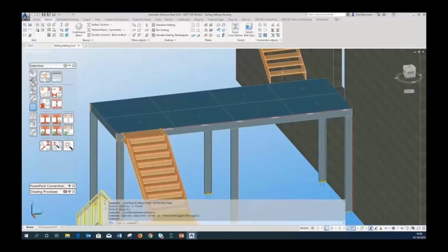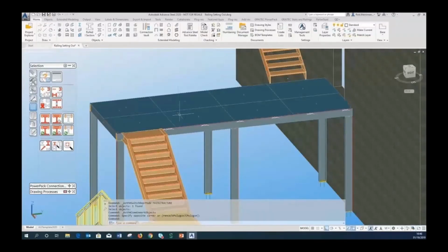And another way you can do separate lengths of railing to manage the panels is to actually use the macro on separate occasions. So on this platform here, I've marked out where I want some posts on the white dots. I'm going to use the railing macro to go between these different dots. There's the first post, that's the end. I'm not going to go all the way in one, I'm going to split it into 2 portions.